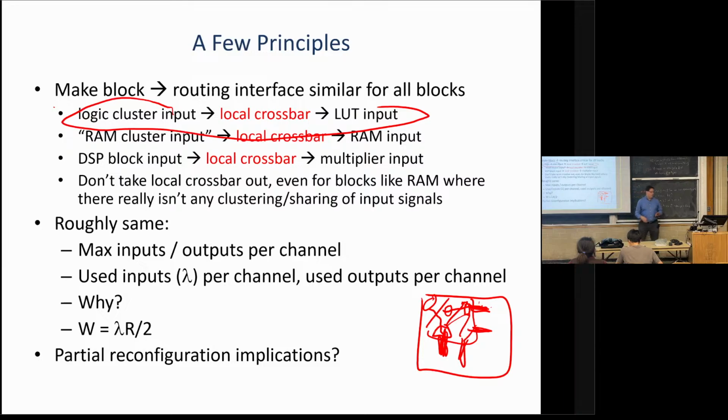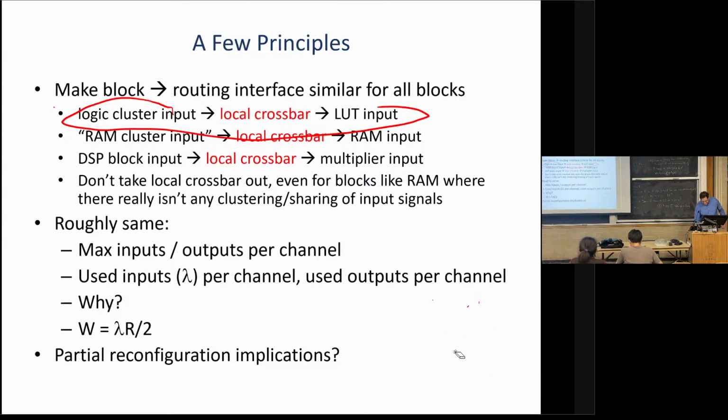We're very proud of it. We're getting ready to ship it with Stratix 5 and market it. And then Xilinx did exactly the same thing in their CAD tools. So it is a good idea. It's going to be a lot harder to market being the second to do this. So that's too bad, right? Yeah, this was purely at the CAD level. You just change how the CAD tools work. They would automatically insert the LUTs on both sides, lock them down near the edges, and then basically the routing problem is no harder.